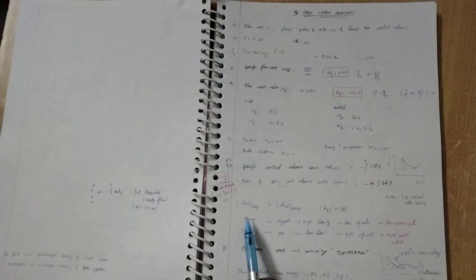For a pump we need to give much less work, but for compression we need to give much more work. Because a liquid pump handles liquid of higher density, there is lesser specific volume, so less work. But for gases, since it is a compressor, gas has lower density and higher specific volume, so we need to do more work. Generally compressor work will be minimum in an isothermal process. Whenever the process is isothermal, the compressor takes minimum input. You can see how much the reduction is in the entire volume, meaning the work done.